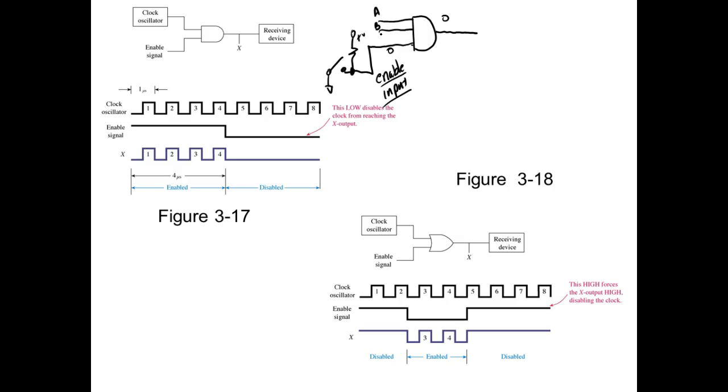Right? Okay. If I come up here and make this a 1, then my output would work like a what? So if we come over here and I start this off now and I say A, B, and out here I put enable. Okay. So let's start off with this right here. Okay, so the output would be a 0.